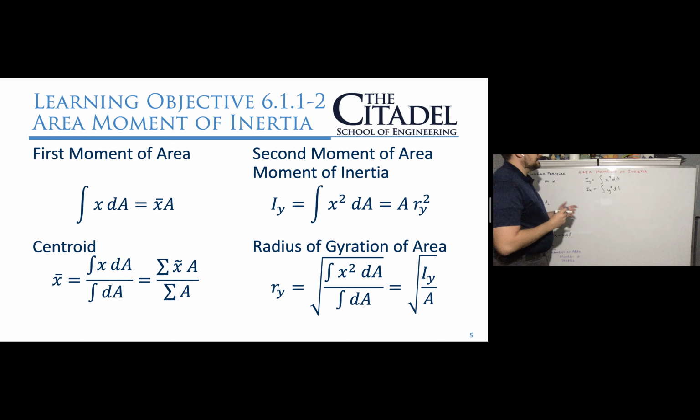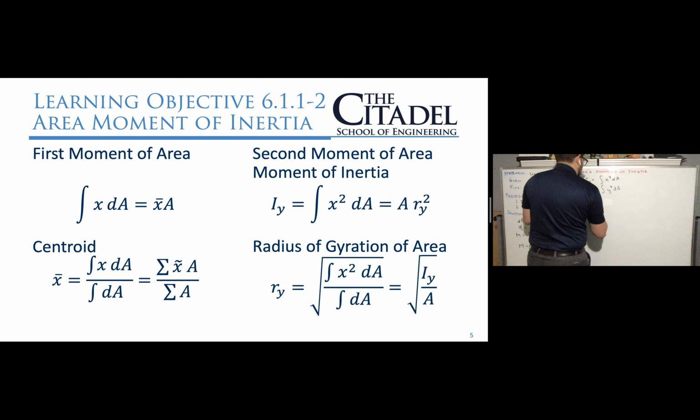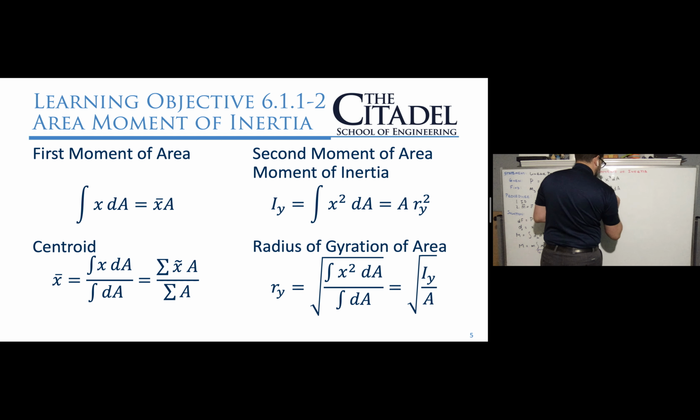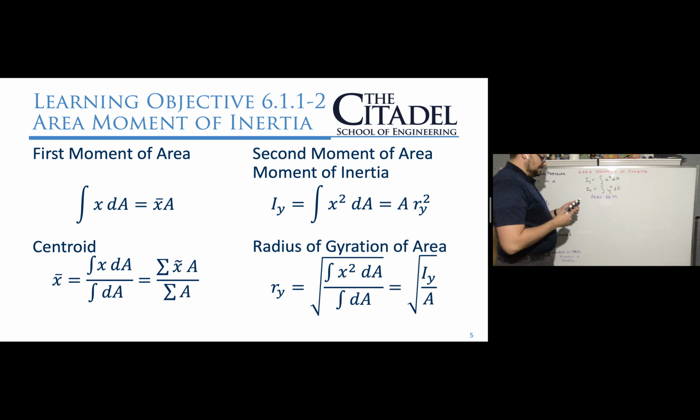And so in each case, we have the perpendicular distance back to the axis squared, because remember, area moment of inertia is the second moment of area. So we have two perpendicular distances times the differential area. You can find this in your FE reference handbook, on pages 35 and 72. Okay, so this is stuff that's in your FE reference handbook. You don't have to remember it.